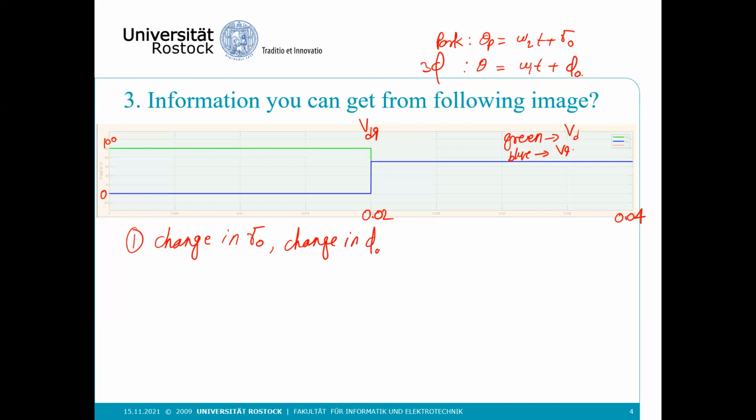It can. Why not? Your three-phase grid voltage angle can also jump, right? It's a sine waveform, and it might happen your phase angle has jumped in the three-phase system, and you have the same Clarke transformation angle. Yeah. So this is also possible.